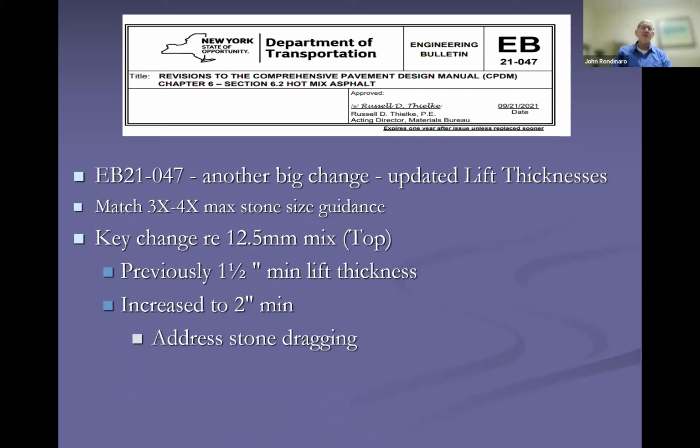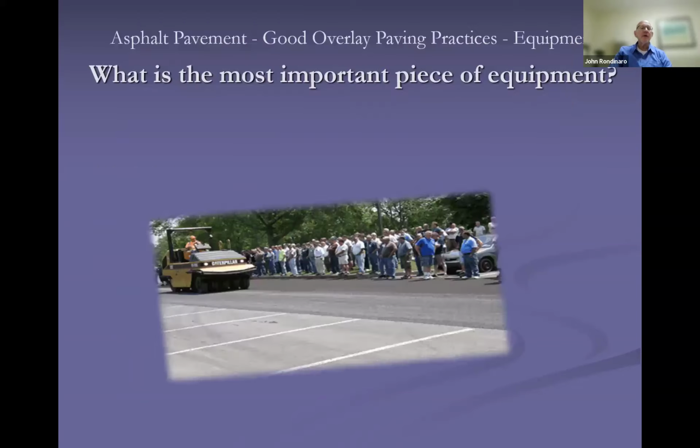That means that half inch max size stone. And so the research, the standard practices now, the accepted practices, is that you really want 4 times that nominal max aggregate size. So 4 times a 1/2 inch is 2 inches. So that's going to give you your 2-inch minimum.